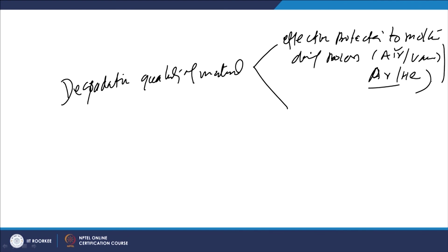If very good control over the environment is maintained, and the molten metal is well protected from undesirable interactions with atmospheric gases by the presence of inert gases or vacuum, then it will lead to the reduction or absence of inclusions or pores. These in turn will increase the soundness and quality of the surface modified layers.